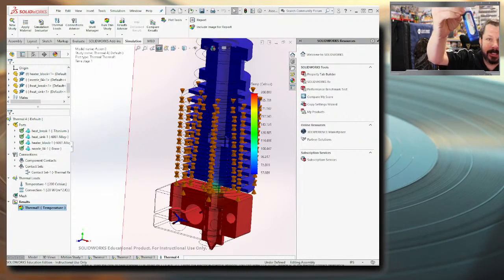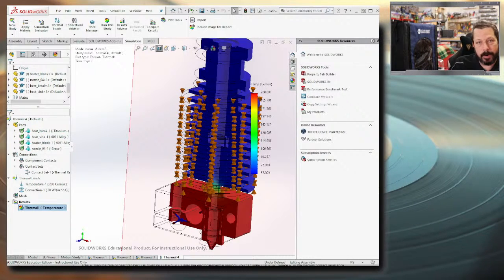It doesn't matter if it's this or not, but I use something that can mark on the wheels, and I put a little white mark on them, particularly the ones on the gantry that are moving up and down, so you can see that they're turning, and they're all 6 turning. If you see that they're not all 6 turning, then you might check and see if something's come loose. You should be able to get all 6 of those wheels turning.